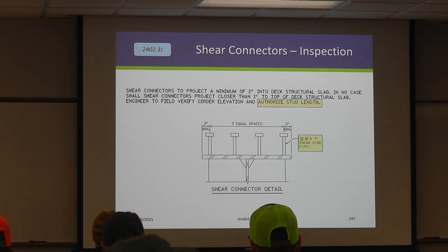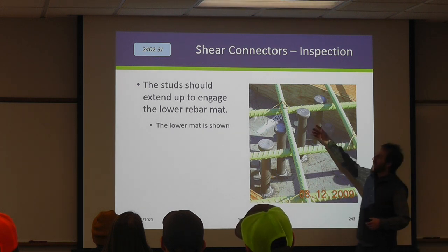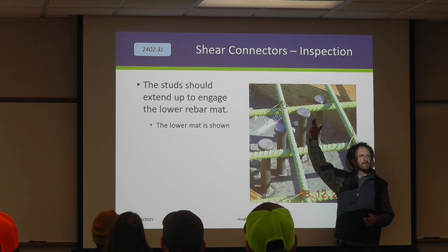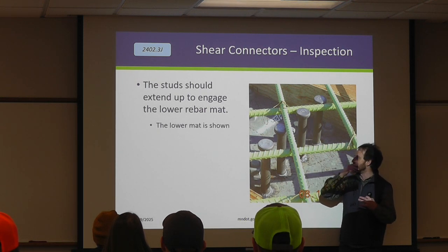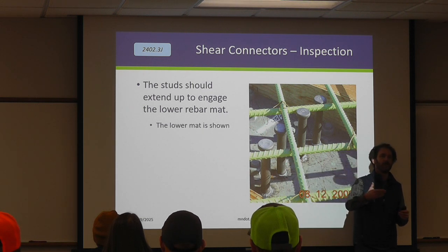That has happened because we do require that these shear studs are engaged in the lower mat of steel. And so you can see how this head is up into the bottom mat of steel here. This is probably more common of an issue on pre-stressed beams because we can't control the camber as much. But they do have to be up in here. And if they're not, we need to mitigate that.